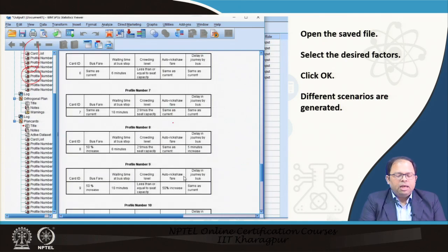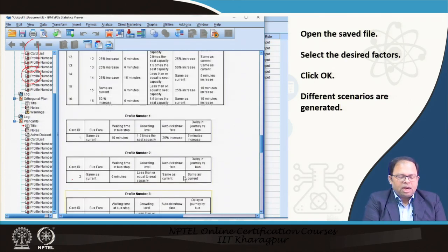Individually each of these cards is given, and we can use each of these cards for one surveyor, or for one surveyor we can give 2 or 3 cards, and for each card he can give his choice and we can record the choice. In this way we can also increase the response. That means if we survey 100 persons and if we give 3 cards to each one of them, we can have around 300 samples of data, which we can finally use to do a regression to determine the mode choice model results and all. The modeling part will be taken up in later lectures, but this lecture actually shows you how to create the choice cards using software like SPSS that we have used over here, and the basic principle behind the fractional factorial design.